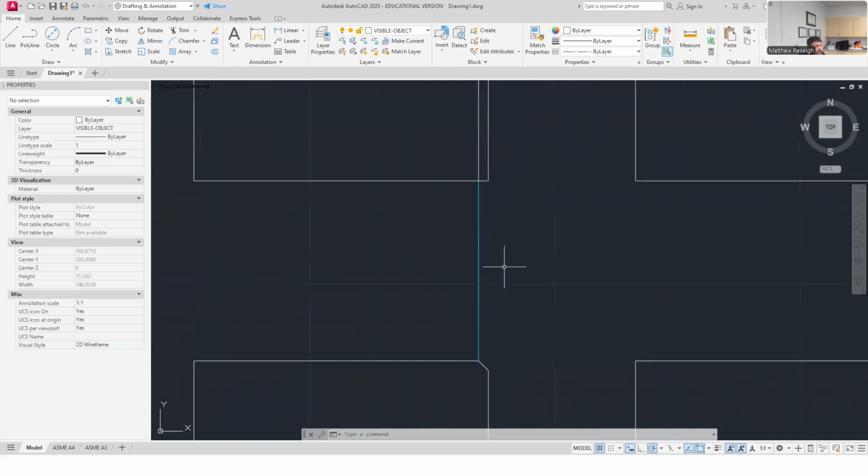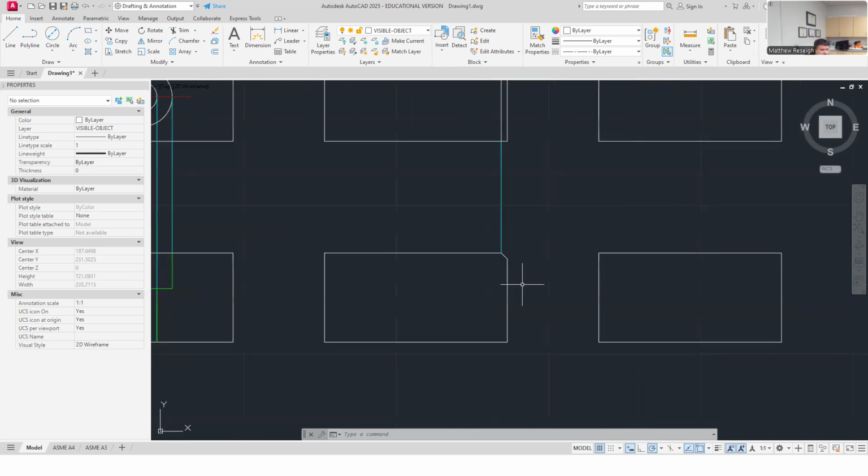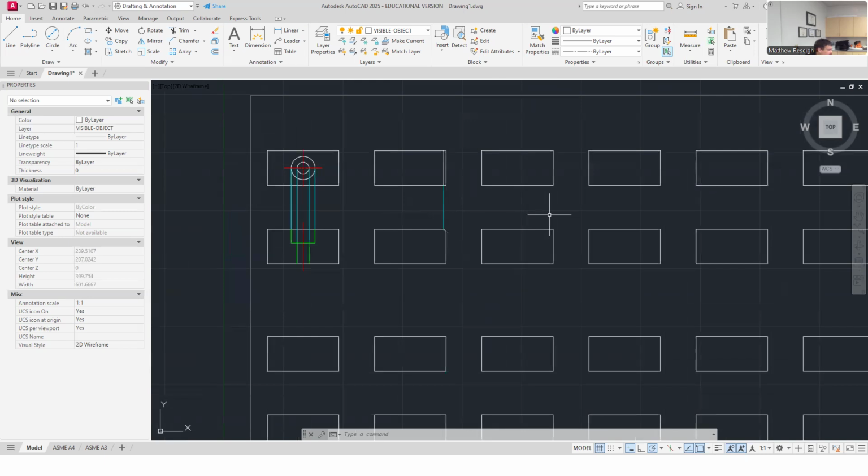And that's why we need multiple views of objects as we draw all the rest of the semester. In some views, some things that we need to dimension are foreshortened, and I need another view where that is actually the true view to be able to pull dimensions. And so we'll use that concept a lot. And so I like to explain that here. But that's really all the construction work I would need to do on that one. That one is the chamfer, right?